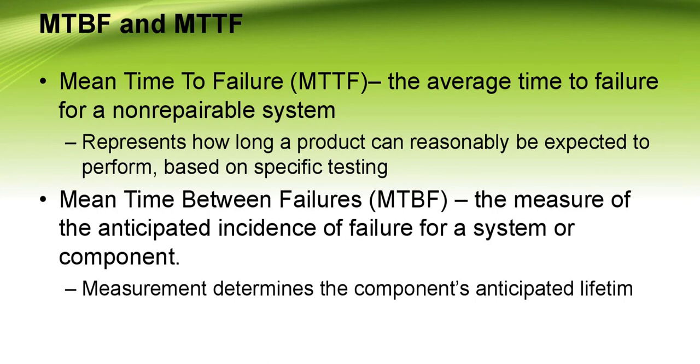Knowing the general reliability of hardware is vital, especially when it is part of a large system. MTTF is used for non-repairable products. When MTTF is used as a measure, repair is not an option. Mean time between failures, MTBF, is the average amount of time that passes between hardware component failures, excluding time spent repairing components or waiting for repairs. MTBF is intended to measure only the time a component is available and operating.